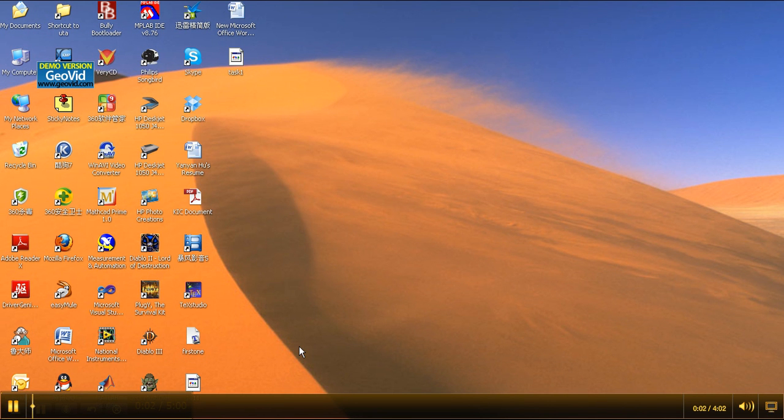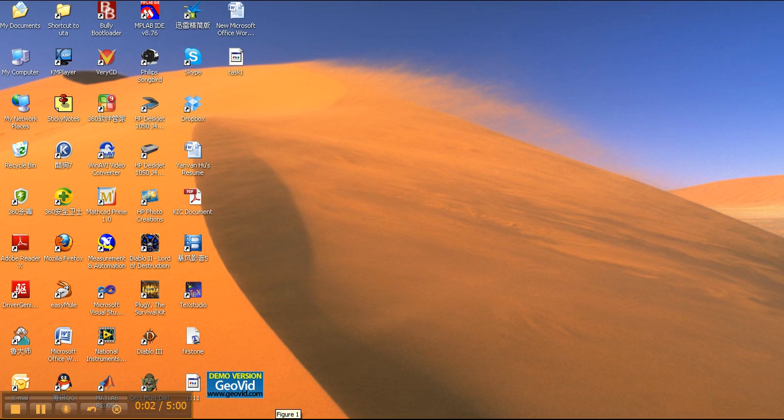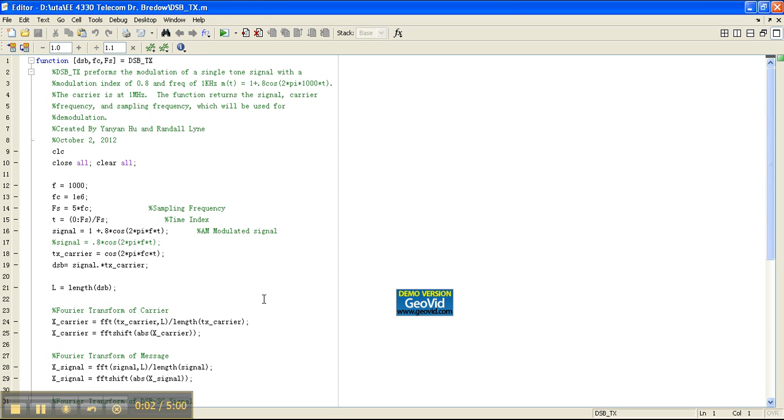My name is Randy Line, and I'll be discussing the next part of the project, which first will be the double sideband suppressed carrier modulation for a single tone. Here's our code. We have the tone frequency at 1000 hertz and the carrier frequency at 1 megahertz.